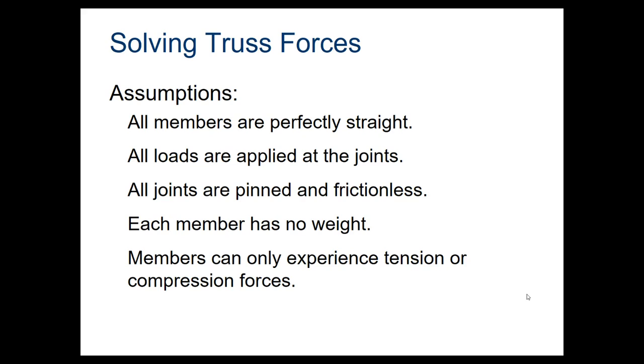All joints are pinned and frictionless. Again, nothing's really moving, so the fact that they're pinned and frictionless shouldn't affect anything, but it's not necessarily true. Because obviously we said earlier that most of these things are either welded together or they're going to have bolts or rivets that hold those things in place, so they're not going to be able to move. And so we're ignoring those forces that would happen if that happened.